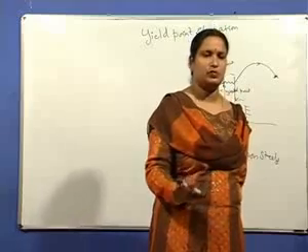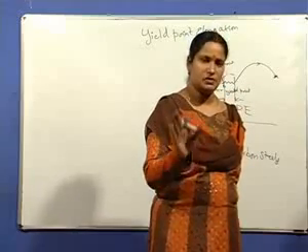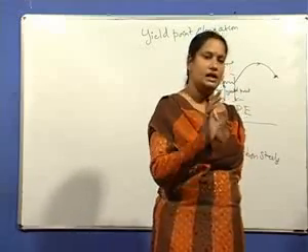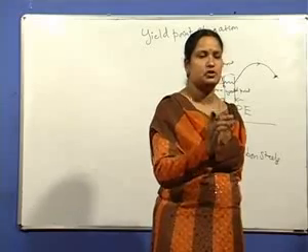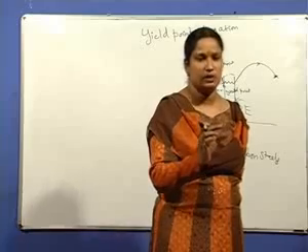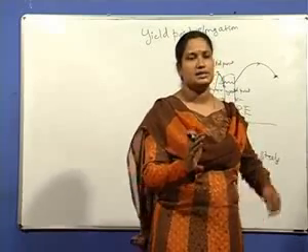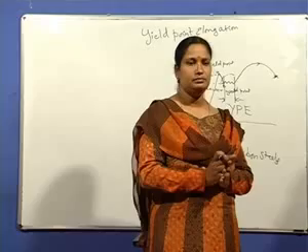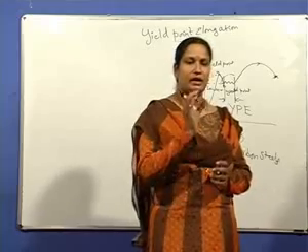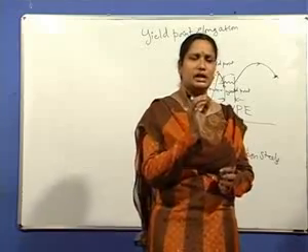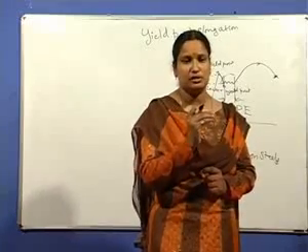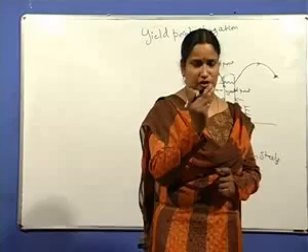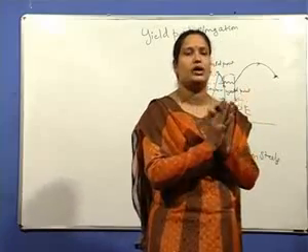So this is the case for substitutional. If the substitutional solute atom is slightly larger, it occupies the position below the edge dislocation where the lattice is expanded. If the solute atom is slightly smaller, it occupies the position above the dislocation where the lattice is contracted.